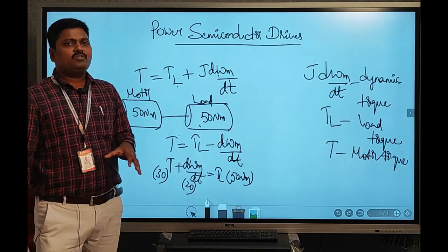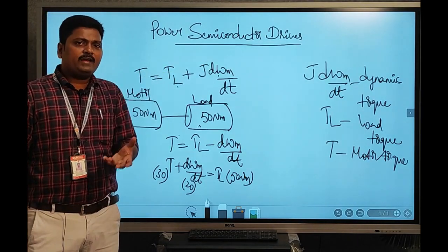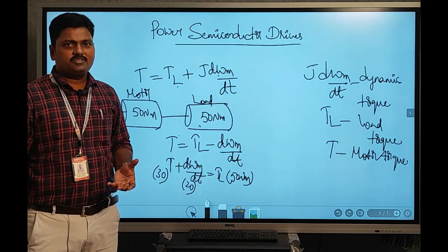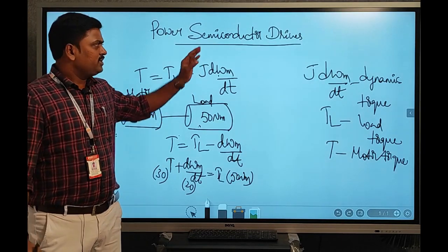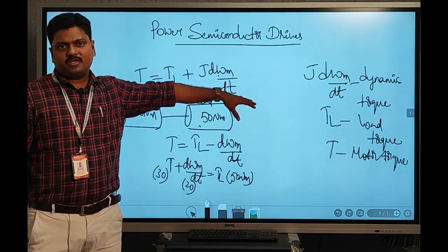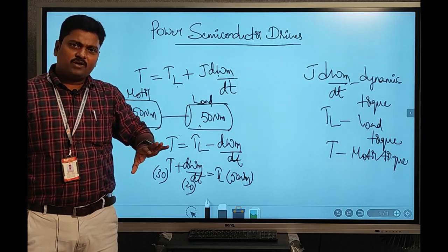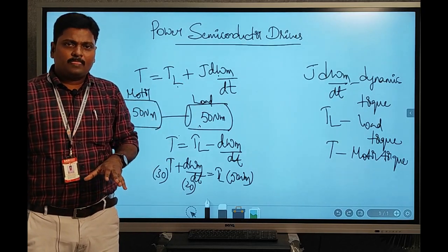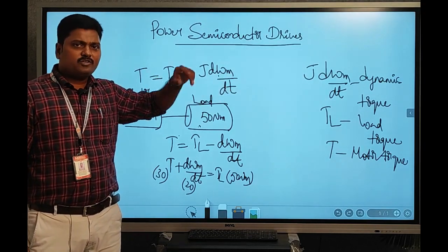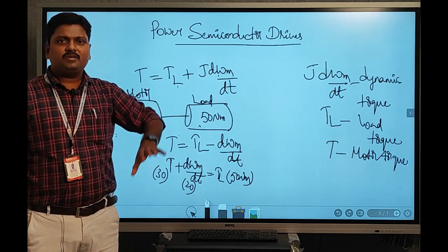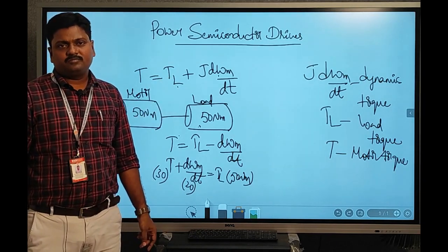So depending upon the type of application, this moment of inertia will act in such a direction. So every analysis of the drives, whether it may be DC drives or AC drives, whether it is controlled by rectifiers or choppers or inverters, this fundamental torque expression will come into the picture, and the analysis will be made with the help of this fundamental torque expression.